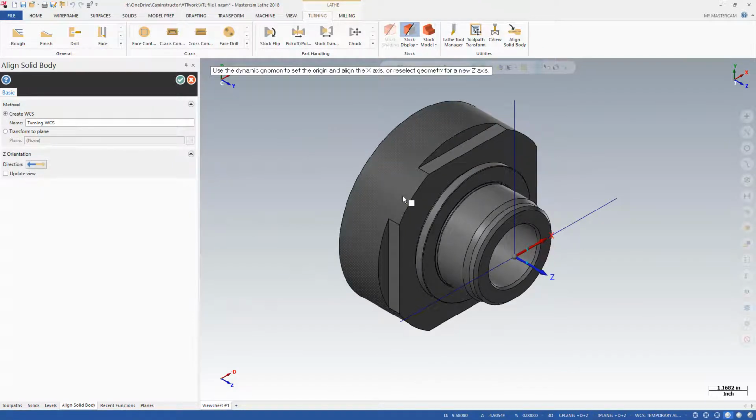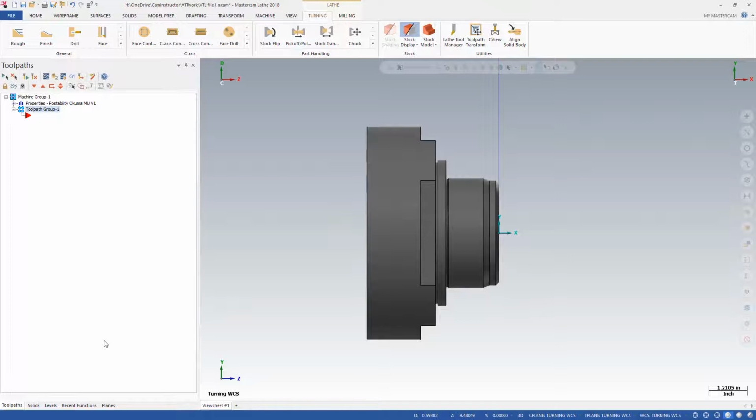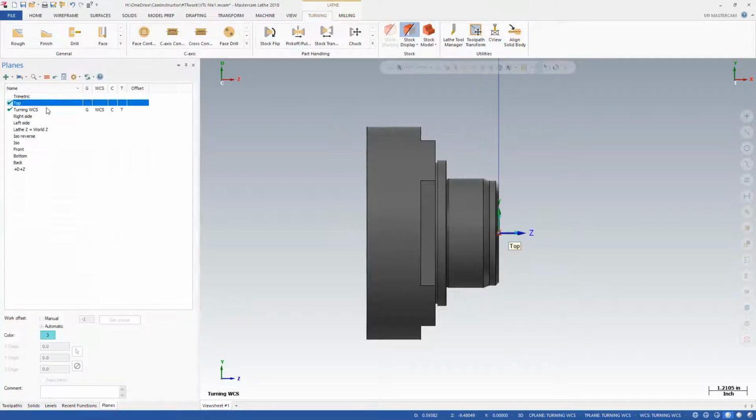If needed, the Z-axis can be moved so its origin matches that used for Z in the top plane. Click on the X-axis and move it until it is aligned in the correct orientation depending on your tilt axis. The newly created plane can now be seen in the Planes Manager.